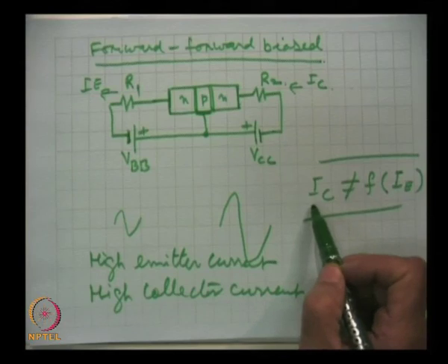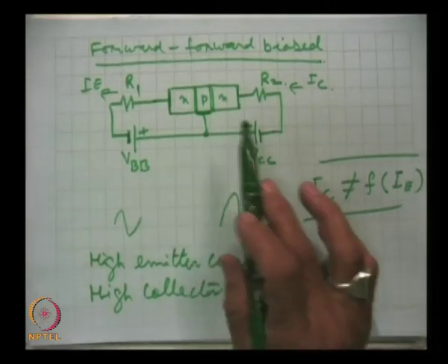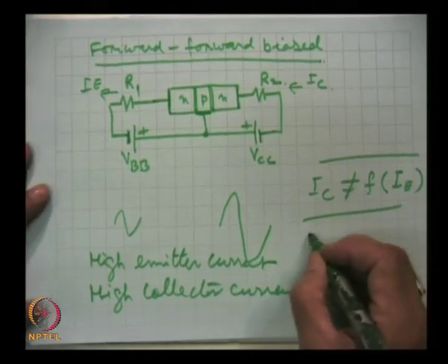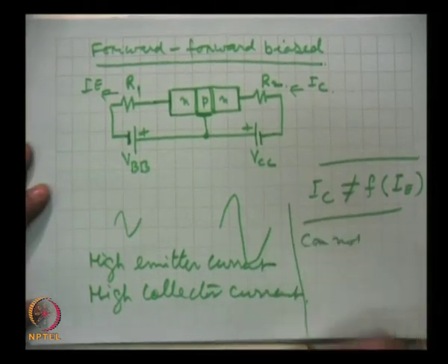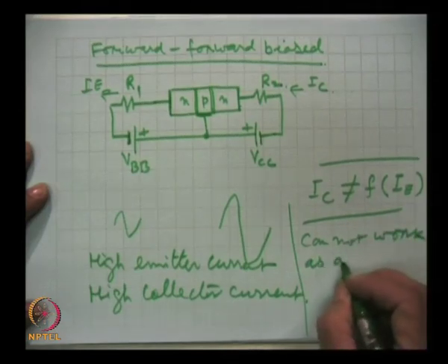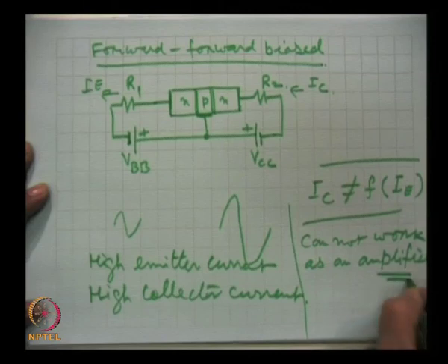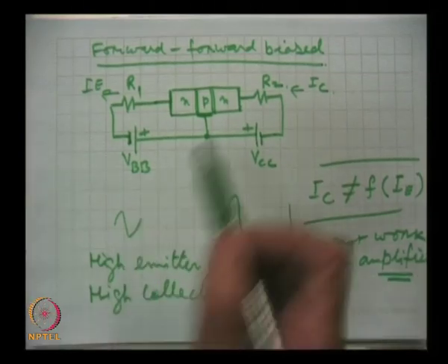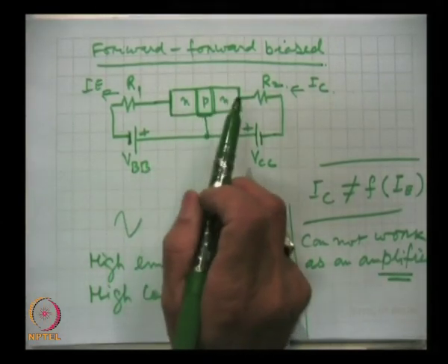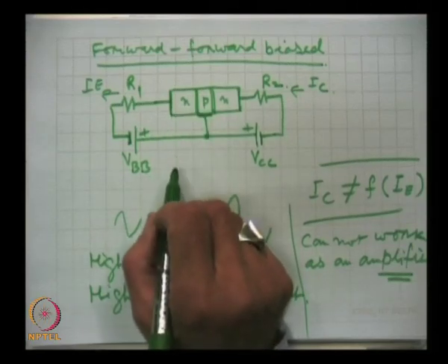Since the collector current is not a function of the input current, this arrangement cannot work as an amplifier, but we will see that in switching states this situation will represent one of the states of the switch.